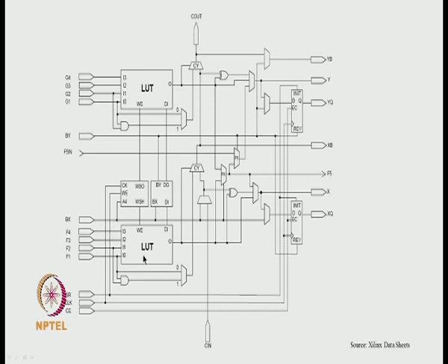Okay, now you can use this. You can see that this is the write enable and the data input, because internally you can assume flip flops. The flip flop output is muxed to the O, and the select line of the mux is the address line. That is the read circuit.